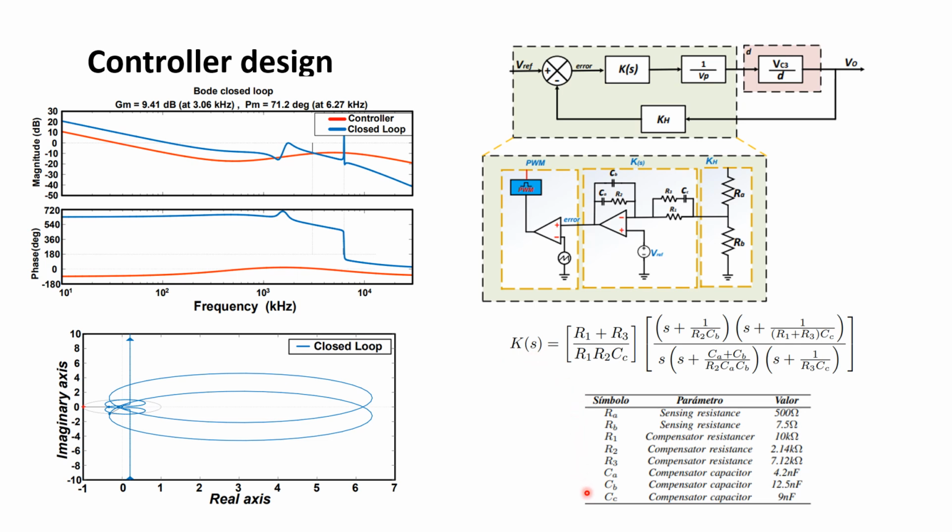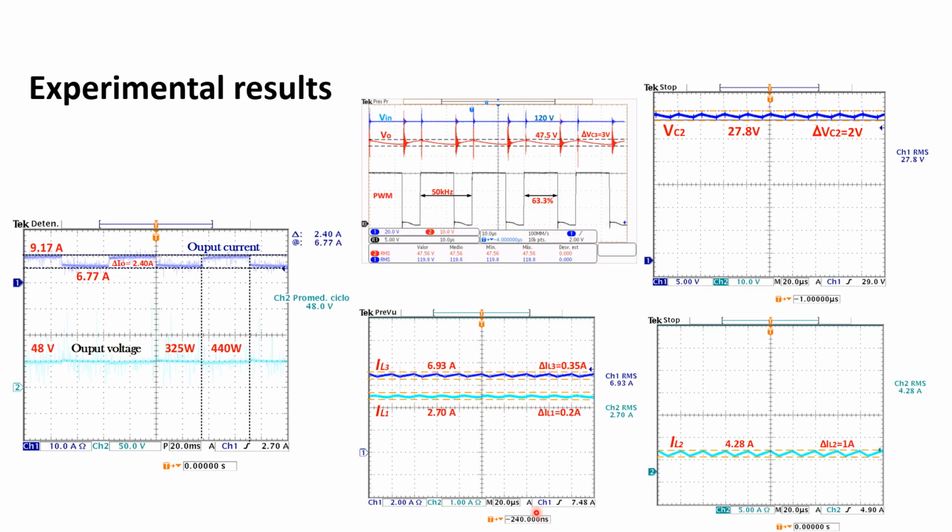It is important to mention that only a voltage loop is used, as the system itself enables cost reduction by eliminating the need for current sensors, thus avoiding the implementation of a second current loop. While a dual loop approach could enhance the system dynamic performance, it would also represent a significant economic cost for this type of system.